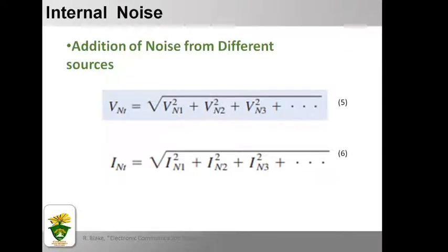Okay, all of the noise sources we have looked at have random waveforms. The amplitude at a particular time cannot be predicted, although the average voltage is zero and the RMS voltage or current and the average power are predictable and not zero. Signals like this are said to be uncorrelated.